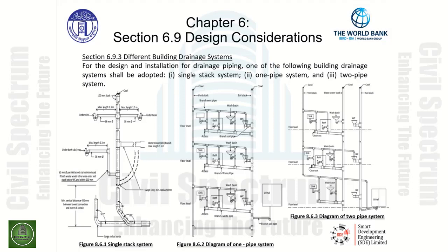The diagram of the one pipe system is illustrated accordingly, where we have a soil stack indicated on the right-hand side and individual vents that connect fixtures that tie into the soil stack horizontally. All of the venting ties into branch vents which run horizontally and connect into the vent stack.